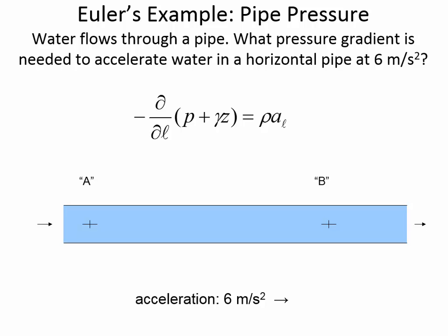Now what are the units? Kilograms, meters per second squared, divided by meter cubed. Okay, now a kilogram meter per second squared, that's a Newton. So that's like saying negative 6,000 newtons per meter cubed. And we want the units to be, for a pressure gradient, Pascal, which is newtons per meter squared, divided by meter. So did the units match up so far? Yeah, newtons per meter squared divided by meter, that's going to be the same as newtons per meter cubed, right? Which is what we've got. So we can rearrange and write this as negative 6,000 pascals per meter. And that will be our final answer. Let me bring that up on the screen so that it's included in the lecture video.